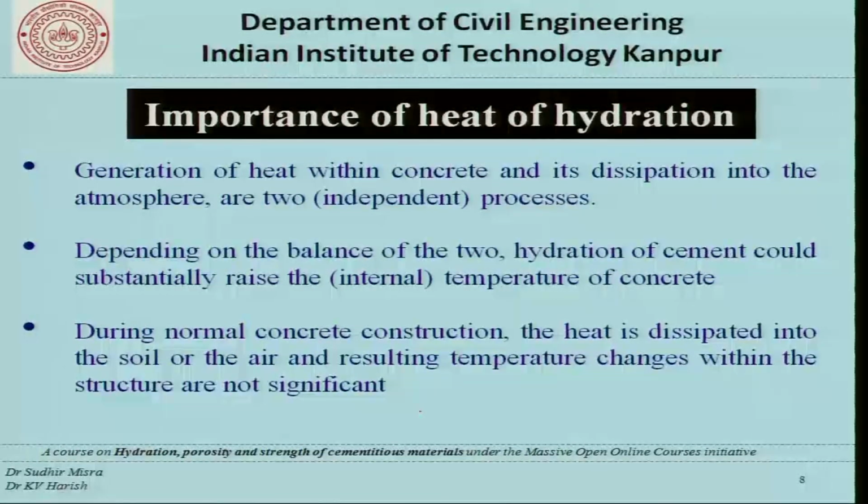As far as the importance of the heat of hydration is concerned, the generation of heat within concrete and its dissipation into the atmosphere are two independent processes. What we must understand is that if we take a block of cement paste or mortar or concrete, this block has a certain amount of cement which has a certain amount of heat which will be liberated if complete hydration were to take place.